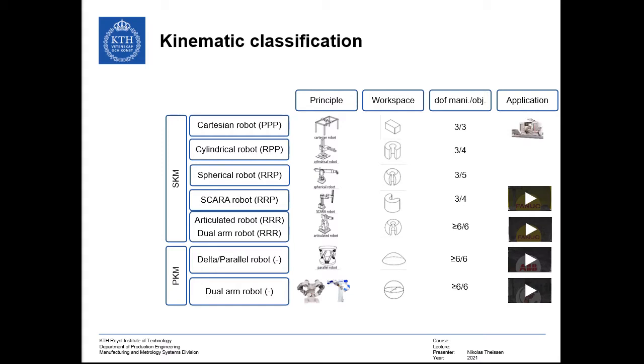So, a manipulator is a machine in which the mechanism usually consists of a series of segments jointed or sliding relative to one another for the purpose of grasping and/or moving objects, pieces or tools, usually in several degrees of freedom. In order to do that, the manipulator consists of links, which are rigid bodies, and joints, which enable the relative movement between the adjacent links.